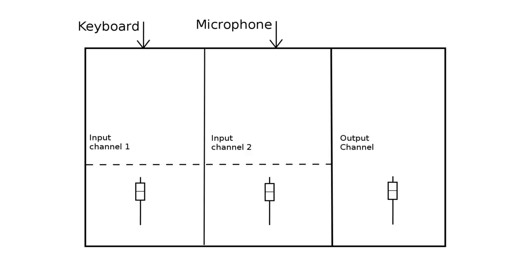In order to achieve this, there needs to be another control on each input channel, a control which adjusts how much signal reaches the channel fader in the first place. This control is typically called a gain control, but may be referred to as a preamp control. Gain controls normally take the form of a rotary knob and can usually be found near the top of each input channel. A useful way of understanding this is to think of the gain control as being a kind of inlet valve which regulates how much of the source signal gets allowed into the mixer.